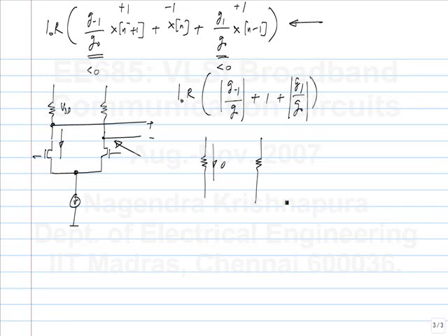So I have something like this, and to get the maximum positive voltage, I have to have this as 0 current. I can have it as some other current, in which case it will only be worse. I can have this to be 0, and what should this be? This is basically I naught times the sum of the absolute values of the coefficients. Now I can make both of the currents larger than this, in which case the common mode will only drop.